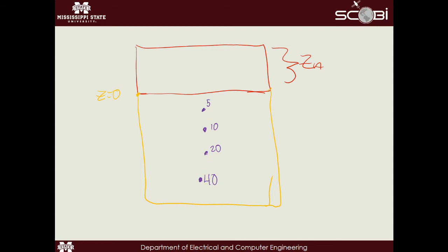All right, so with a discrete slab function, what that fit does is it assumes that because you only have 4 soil moisture values, each of those values is going to represent a piece of the soil moisture profile. And what it does is it takes the midpoint between adjacent soil moisture probe values, or I believe the input calls it.